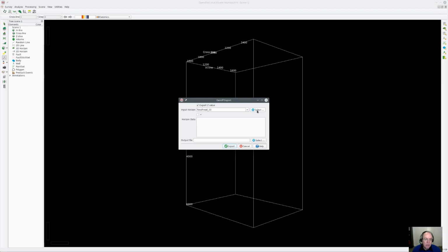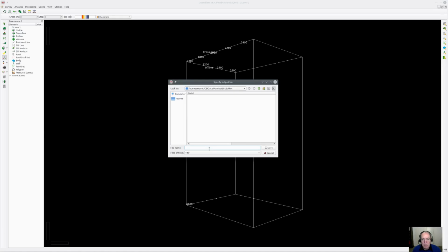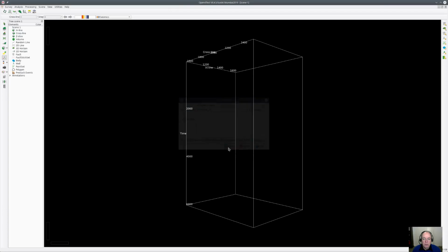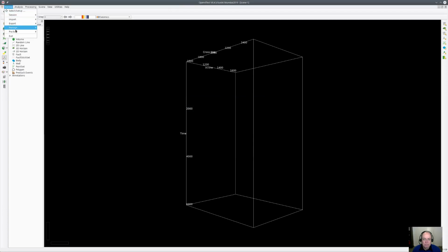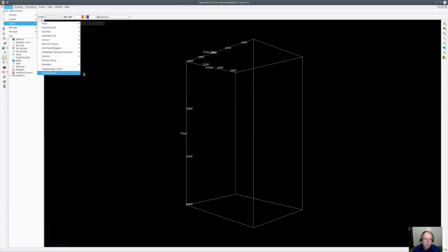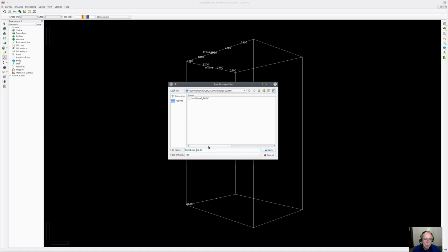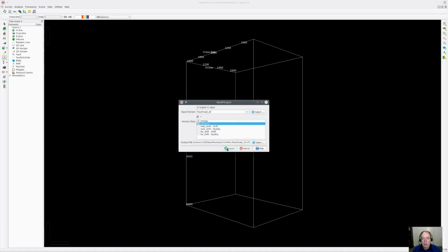Geotiff 3D horizon export is also straightforward. It is possible to export the Z-grid and horizon attributes into a single file. So here I am exporting two Geotiff files, one with the regional Z-grid from the previous demo, and a horizon from the 3D survey, which also has associated horizon attributes. All these files that have been created by the plugins can be easily displayed in a GIS package like QGIS.